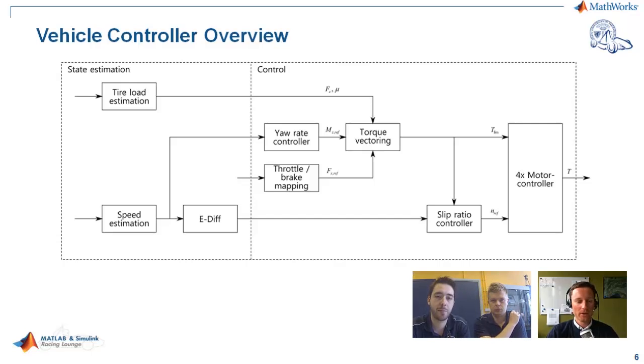Yes. Okay. Then coming to the speed estimation, are you actually measuring the wheel speeds, or what are you doing when you want to estimate speed? Well, for the speed we actually use several different methods at the same time. We look at the wheel speeds, which we also correct for the distance from the COG and steering angles and such.